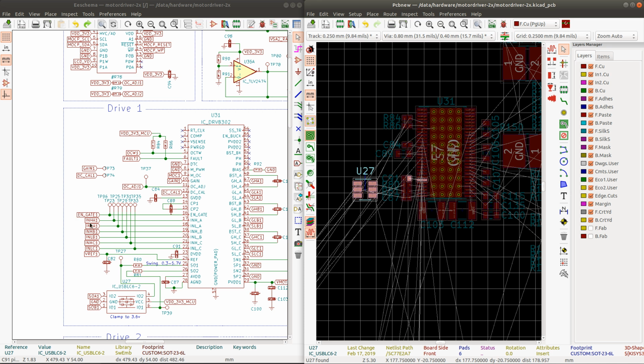So what I do here is that I pass them through the resistors, and then I clamp them with this diode, so that they're always clamped to 3.3 volts. And by adjusting the gain later, I can make sure that the current sensing is within the 3.3 volt range.